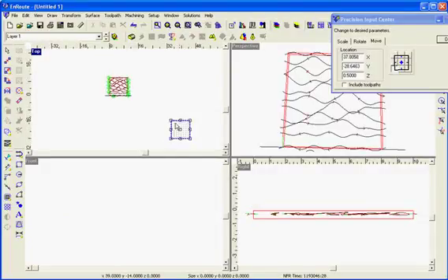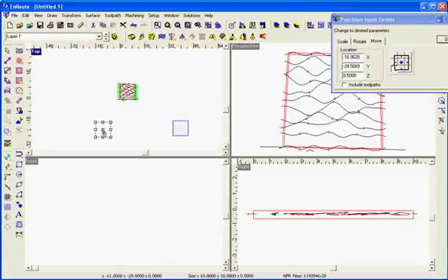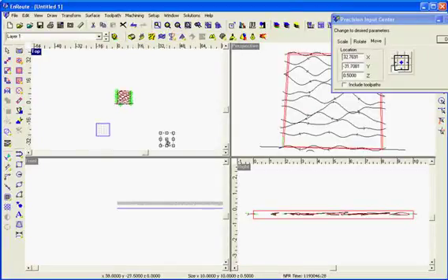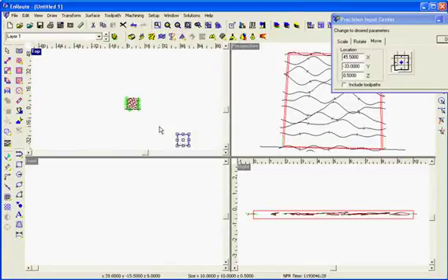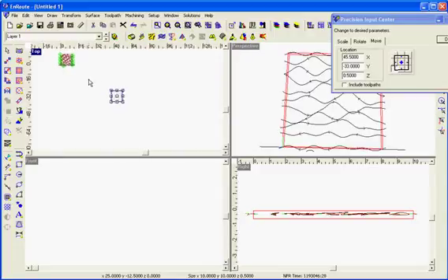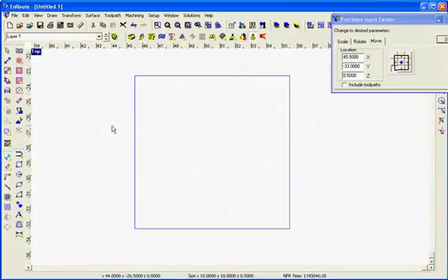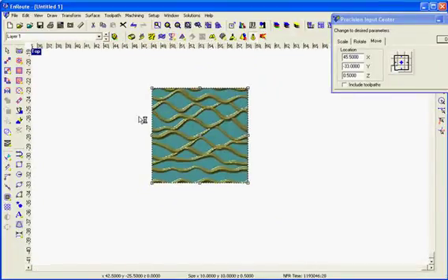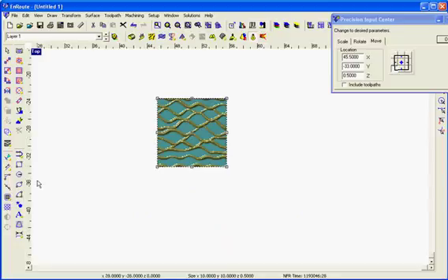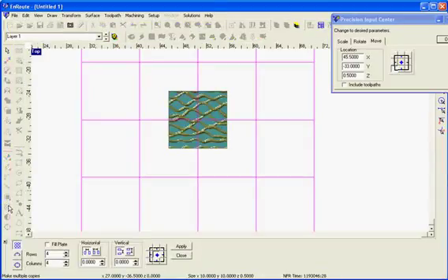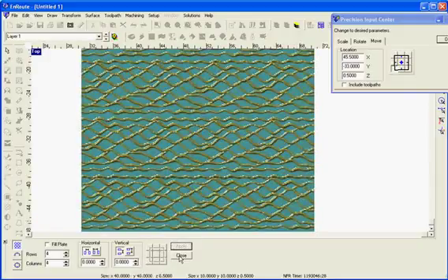During this process, it's likely that because of the merging process, we might be a little bit off from a simulation standpoint with some of these parts, but for the most part, we should see that everything matches up correctly. An easy way to do this, first we'll come in here and zoom in on this a little bit again. An easy way to do this is to utilize the multi-copy tool. So I'm just going to scroll back here a little bit, come here to multi-copy, and in this case I have 4 rows and 4 columns with no spacing. I'll hit the apply key and then close,